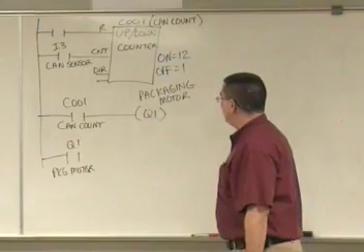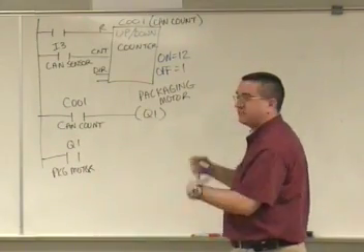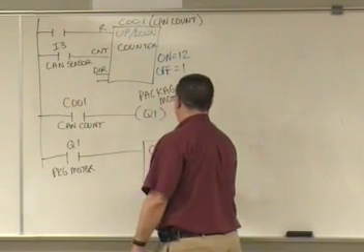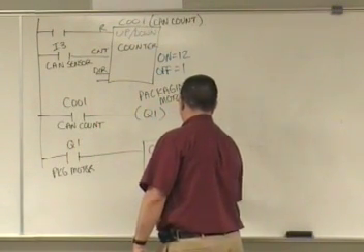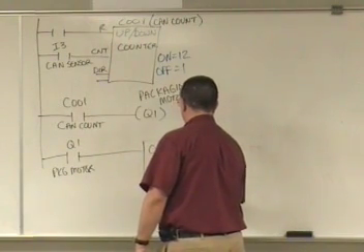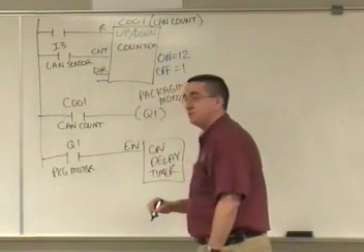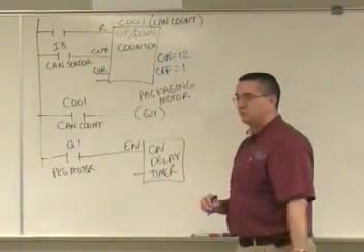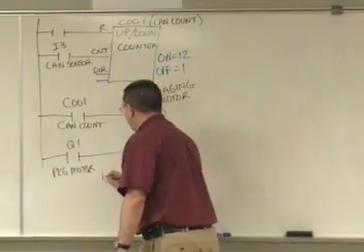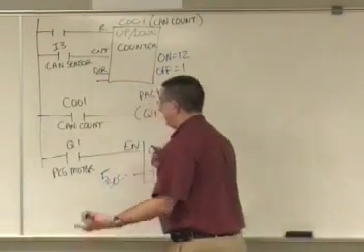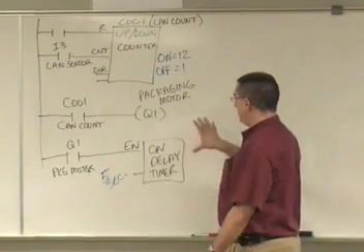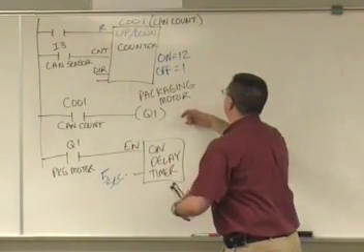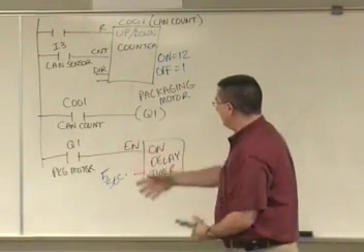Okay. So in this case, we're just gonna time it just to make things work. So if I wanted to time it, I might use an on delay timer. And I know there's an enable pin on that on delay timer. Okay. And I know there's also a blue pin. What's a blue pin? User parameter. And in this case, let's just say that on delay timer runs for 5 seconds. Okay. So when the packaging motor has been running for 5 seconds, I want the packaging motor to shut off, and I want the counter to reset.